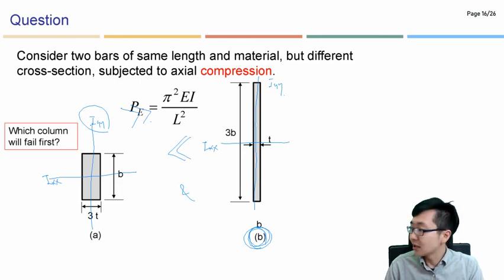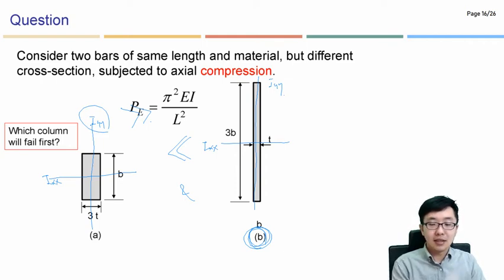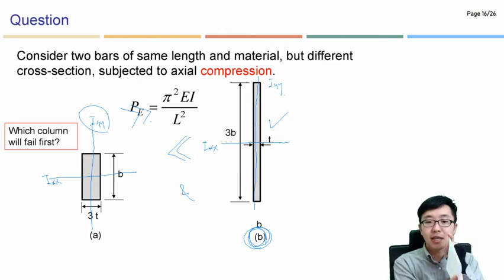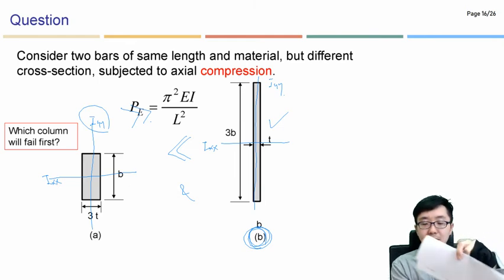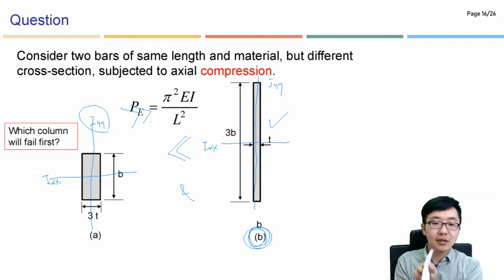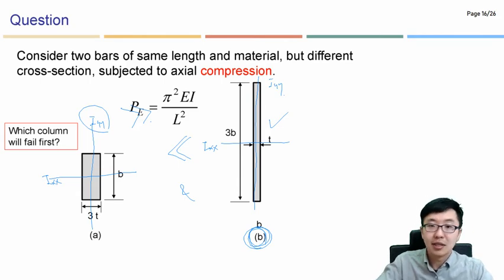So if you don't understand it, you can bring some kind of paper and use it. This looks like this B here, right? And then once we apply the axial compression, it will be buckled this way, like this way. Why is it not buckled that way? Because of the Ixx and Iyy calculation, you can compare them so that you can simply understand what I'm talking about, right?